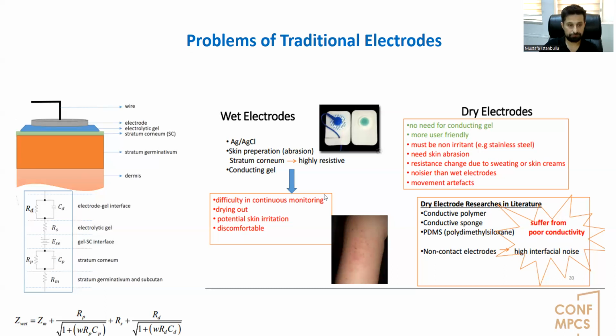Electrodes made of many various materials with different arrangements can be found in the literature. Today, generally silver and silver chloride electrodes are the most widely used in clinical practice due to their low and stable half-cell potential, low noise level, non-polarity, and low metal electrolyte resistance. Of course, additionally, electrodes made of platinum, gold, and steel are also available in practice.